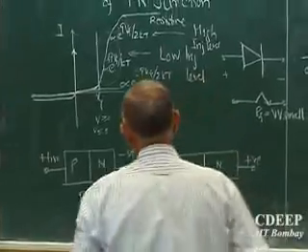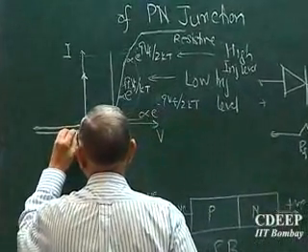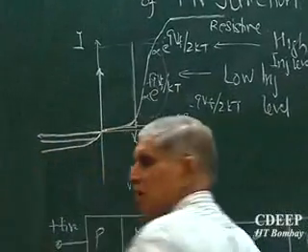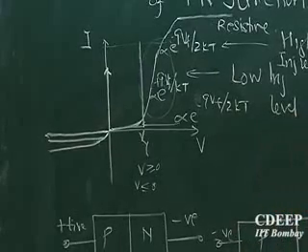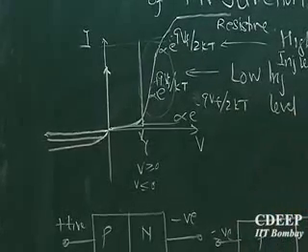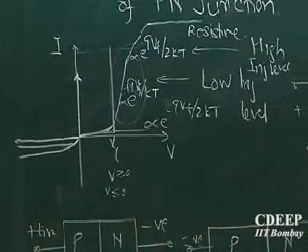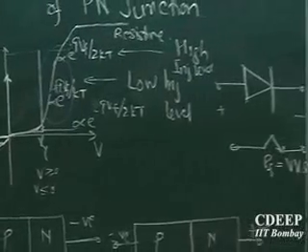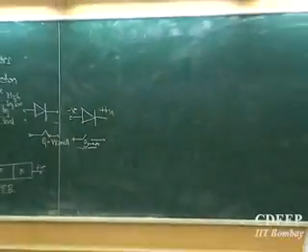Now we see in reality this does not remain constant, but it does change a little bit. Of course I am expanding it intentionally. The current does rise as I apply reverse bias. Though the first theory says it should remain constant, in reality I find it does not. So another theory must be put forward for why this current is not constant but additional current is coming from there.